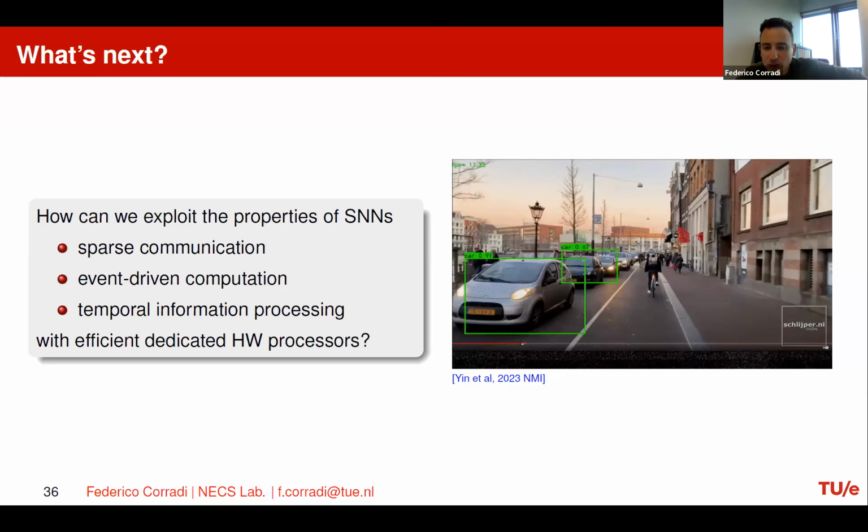There is one question on how the input images and videos are converted into spikes. For this specific network, there are 3 channels: red, green, and blue. The color scale of each channel is 8-bit, 0 to 255, and this is directly injected into the first layer of neurons as memory potential, exciting the memory potential, which is then immediately converted into spikes after the first layer, and then everything else is spike-based.